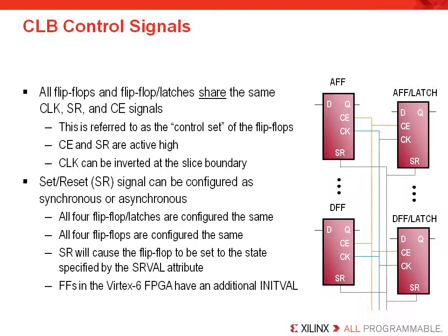All flip-flops and flip-flop latches share the same control signals. The group of associated control signals with the flip-flop is important since only flip-flops that share the same control signals can be grouped into the same slice. This means that if you don't manage the use of your control signals and try to reduce the number of control signals your design has, then you might have trouble getting high device utilization.